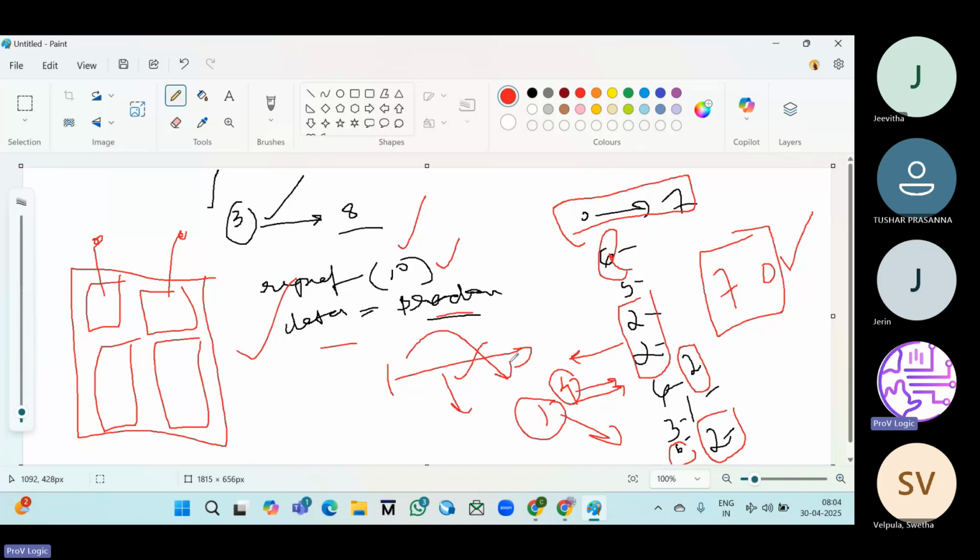See, synthesis is different here. We are talking in terms of the verification point of view. Synthesis, if you want to do that, we can do. Synthesis is different, and test bench verification is different. Here we are running test cases. We are not resynthesizing here.